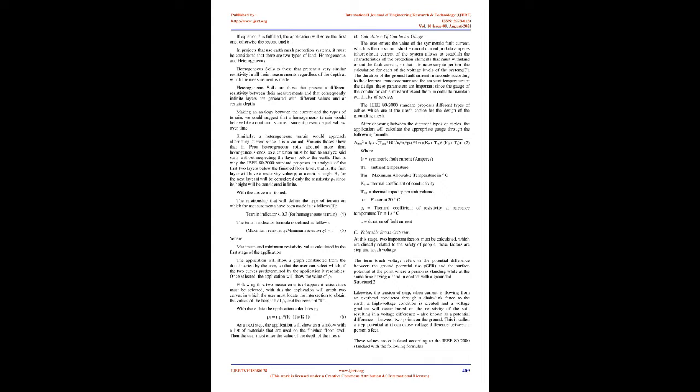1. Function of the application. Define the type of terrain. The application will show spaces to complete resistance values obtained by the user through measurements with the Wenner method, maximum 7. In case the user makes fewer measurements, there will be no need to complete them with 0, since the measurements not completed will not affect the subsequent calculation. The application will calculate the resistivity values based on the values entered by the user and through the following formulas.